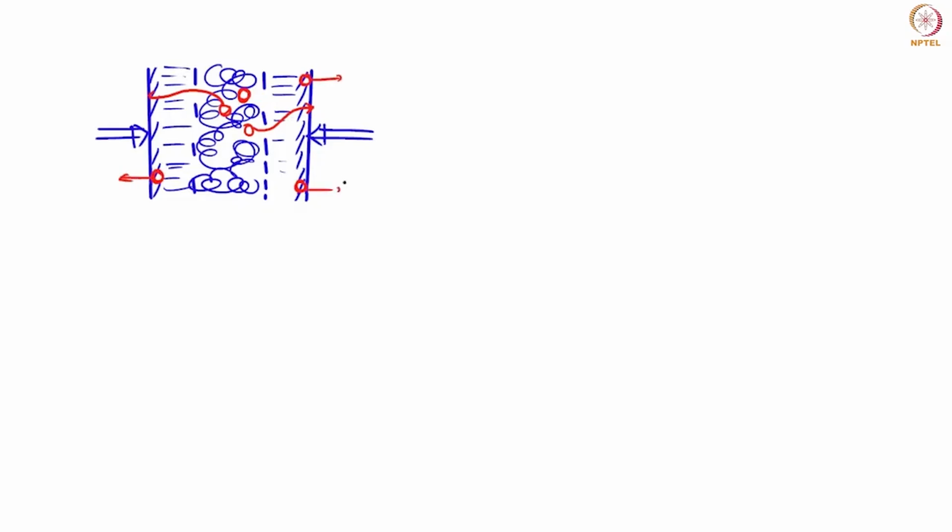So that is basically your problem. There will also be some thermal conductivity difference, because this material is already carbon, let's say at a given temperature, while this material still contains a lot of tars and bubbles. So of course, there is going to be also a thermal conductivity difference. So the temperature which is reaching the core of this structure may not be the same as what you have on the surface.